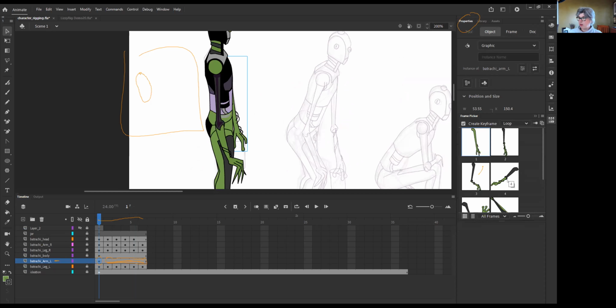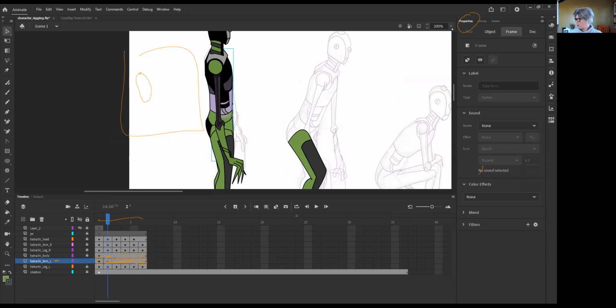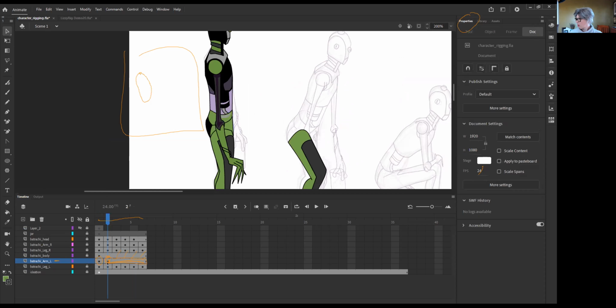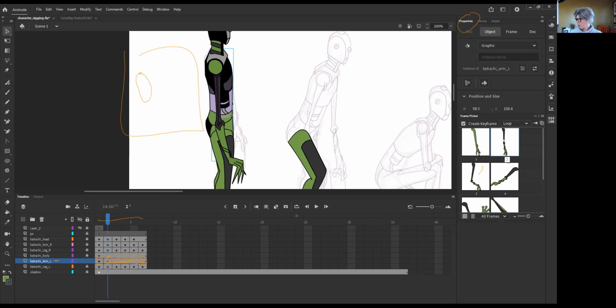And see, that's where you would put it on the timeline using the frame picker. So go further down the timeline, click right here. Yep, and insert a keyframe and go to the frame picker. Good, click on it and then choose the different arm.